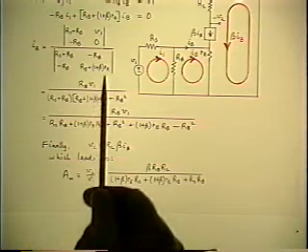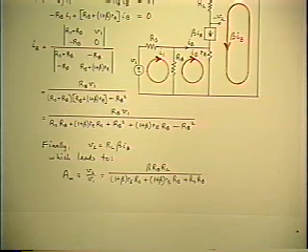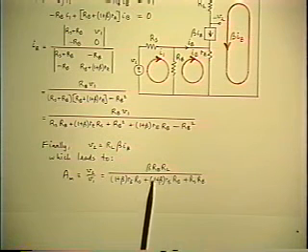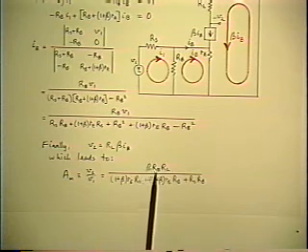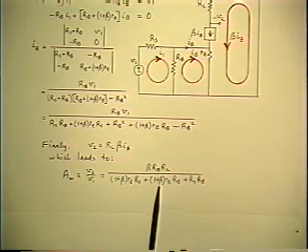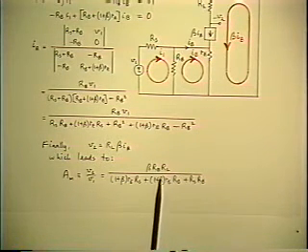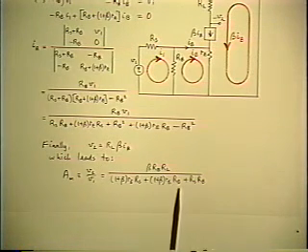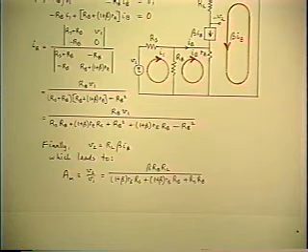This is the example we had first in the introduction. The answer is just the way it comes out of the brute force algebra. No attempt at arranging anything, that's just the way it comes out. And of course, it's the ratio of sums of products of the circuit elements. This was a 2-loop model, so we get sums of products 2 at a time. If it had been a real 3-loop circuit, we would get sums of products 3 at a time. So it's easy to see how the algebra escalates very rapidly when you get to more complicated circuits.